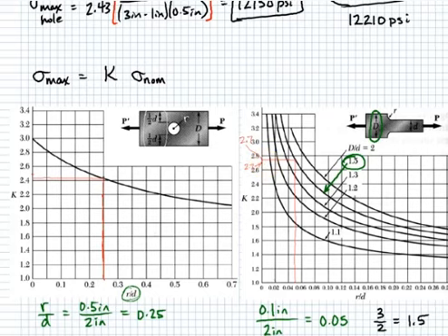What that would do is shift it over to where R over D would calculate to now 0.06 instead of 0.05. So then I could read this line up to where I hit this curve, and holy moly, that gives you a really solid value of 2.6. That's one of the things that we commonly do on exams. We don't always do this, but it is commonly done so that people have a little bit more of a good feeling about it when they've done it right. They can be pretty sure that's probably the number we were shooting for, K, as long as you did it right.